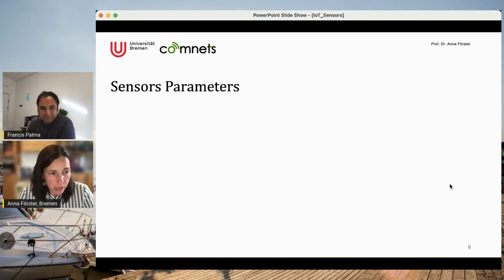With MicroPython you can have some sort of asynchronous programming. You have to be very careful because you're not implementing with individual, isolated processes, but with non-isolated processes, let's say. So if you need to synchronize them, you need to do it manually. You cannot simply fork a process as you would in any other system and say they're synchronized and isolated, so no memory leaks, nothing like that. This is not true here.